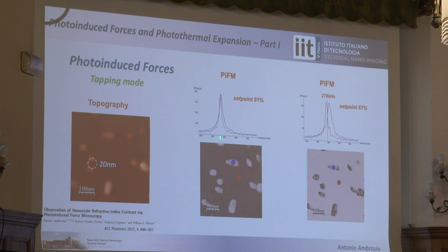Here the modulation is around the first mode of the detection, around 300 kilohertz. This is where these numbers come from. But then you go to the cover slip substrate, you do the same, and you find the red, right? That means that with this set point, they are basically overlapping each other. That means that whatever you set your demodulation frequency in the lock-in, you get this contrast.